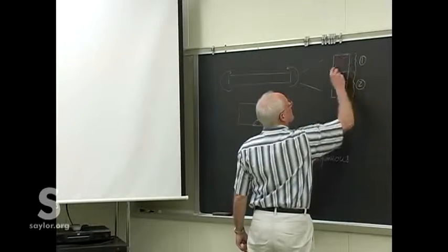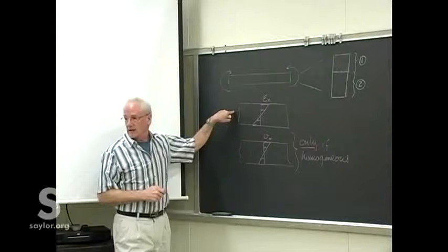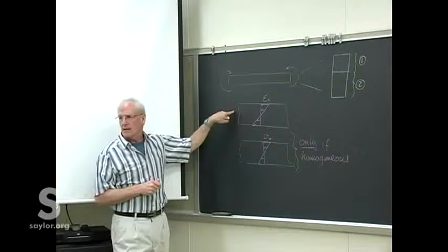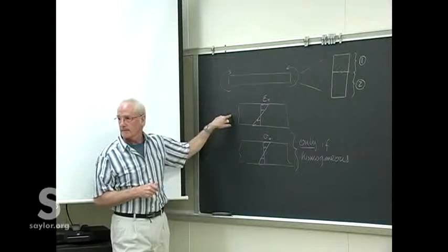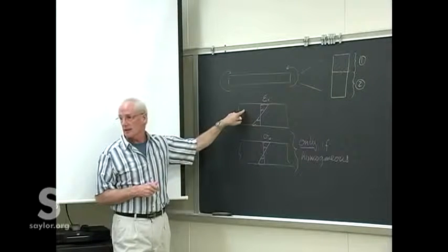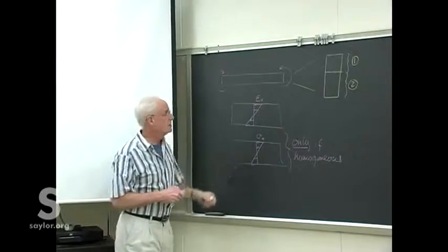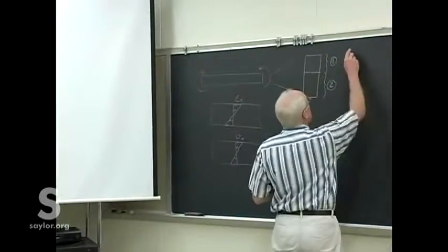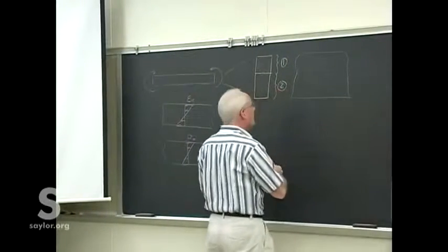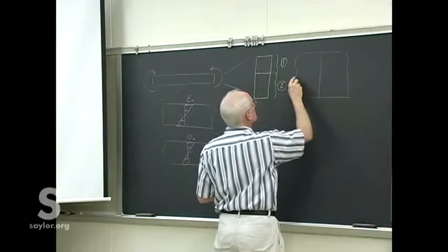So the trouble comes now that the strain will indeed be linear. That doesn't change. That was only dependent upon the cross-sectional area. This came from the fact that stress and strain are related by Young's modulus. If we have a different Young's modulus for the top than we do for the bottom, we can now expect some kind of stress distribution that may look like this.